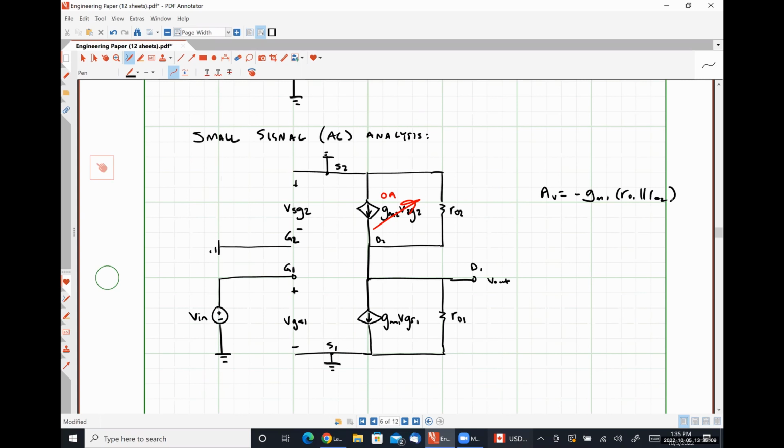And the common source amplifier is also usually used as the second gain stage after our compensation stage, which is just literally a resistor and a capacitor in series, to provide a large amount of gain, to step our small gain from our differential stage up into a large gain. So this simple circuit of 2 transistors stacked on top of each other, 1 PMOS, 1 NMOS, is really a fundamental building block of op-amp design.